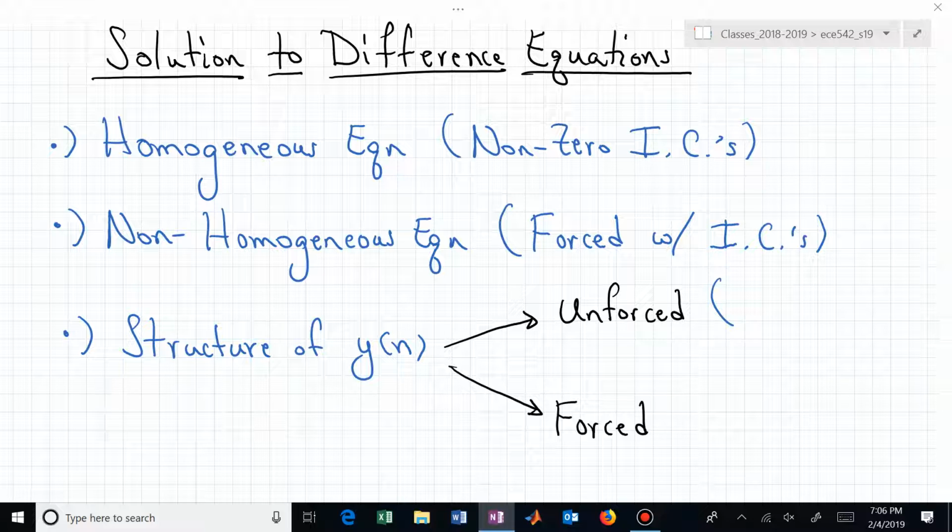All right, so back to the unforced structure of our system. What if I now z-transform that difference equation, and what would I use that z-transformed expression to find the structure for y of n, or how could I use that? Can you find the roots of your characteristic equation and find the natural modes?